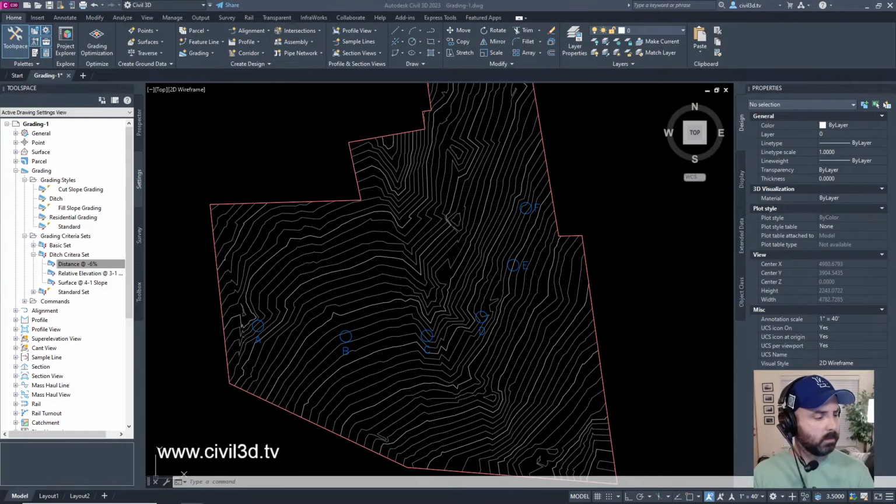Well, maybe you can insert vertexes. I don't know. There's probably somebody out there that knows a little bit about this stuff. But with feature lines, you can essentially grade at different points along just one stretch of feature line.